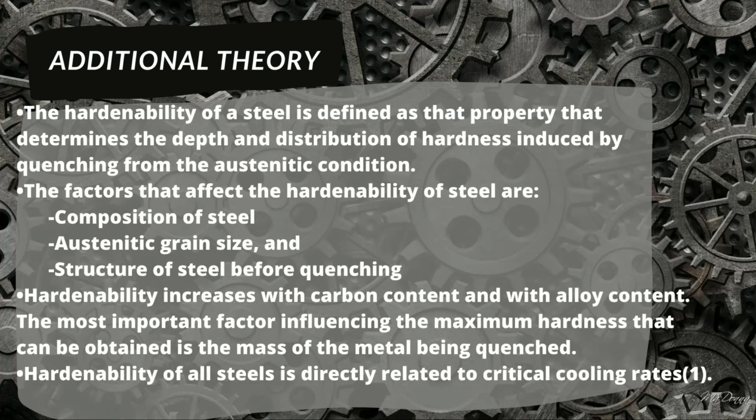Hardenability increases with carbon content and with alloy content. The most important factor influencing the maximum hardness that can be obtained is the mass of the metal being quenched. Hardenability of all steel is directly related to a critical cooling rate. This is taken from the first reference.